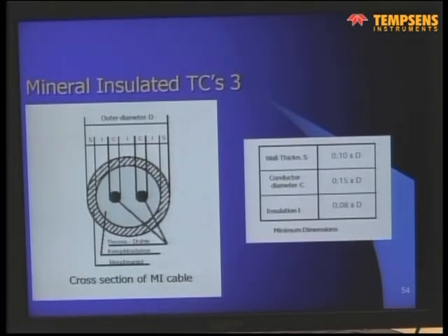If you would like to have smaller diameters, you do not start normally with 1 inch outside diameter. Normally you start with a 1/2 inch pipe or 3/4 of an inch pipe. And then you can draw it down to 0.25 millimeters outside diameter with 2 insulated wires inside.